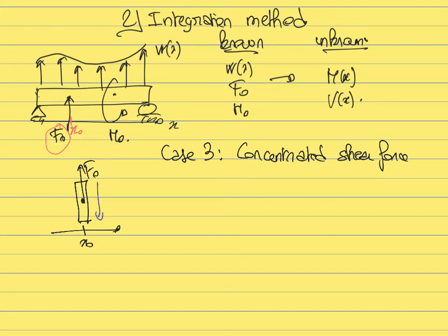So same thing, internal shear at x plus, internal shear at x naught minus. So this is the internal shear slightly before and slightly after x naught. And same thing, the moment. Moment is defined to be positive like this. That is the moment at x naught plus, moment at x naught minus. Same thing, we are going to now write the condition of equilibrium.